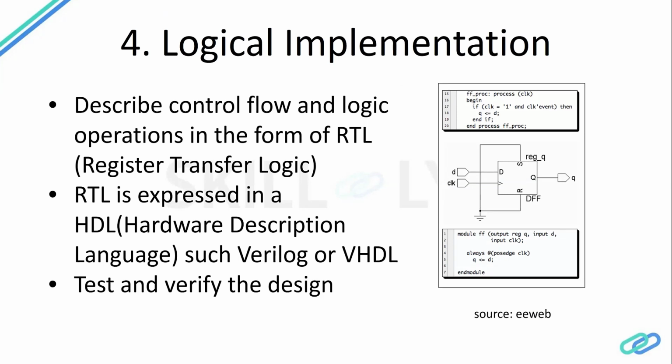In the industry, this RTL is represented using an HDL, which is nothing but a hardware description language. The examples of this HDL are Verilog or VHDL. There are new languages which are also being supported, but across the industry, Verilog and VHDL are the most used hardware description languages. Using Verilog, you can describe the RTL or the logic using behavioral code. It can also give you an understanding of how the design will behave. And once the hardware is defined using the HDL, you can also test and verify it.